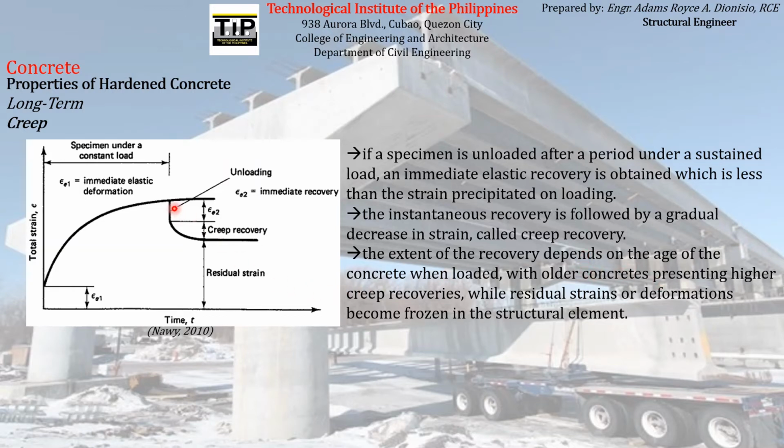Although elastic is not the right term, older concrete tends to recover more strain as compared to fresher concrete, because obviously the older concretes have already achieved their compressive strengths.